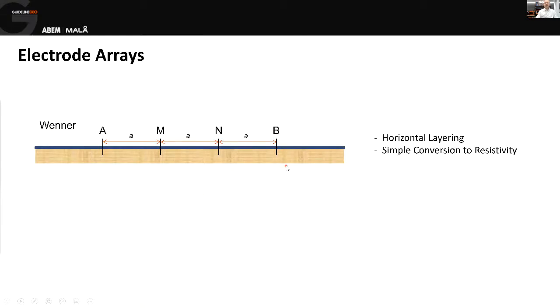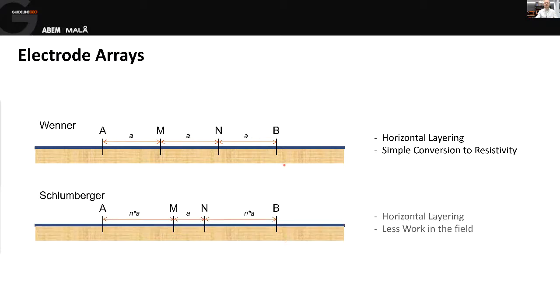We can then decide whether we use what's called a Wenner measurement, we talked about him earlier, or a Schlumberger measurement. They are both excellent for finding horizontal interfaces, so horizontal layers. And we said already that for a 1D measurement, those are our best targets. So these Wenner and Schlumberger arrays will define the contact between separate layers much more closely than some of the other arrays that are available.